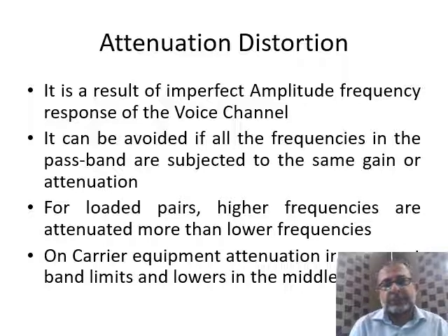Similarly, for loaded pairs, higher frequencies are attenuated more than lower frequencies, and there is a very valid reason for that. In the loaded pairs, we have inductors in our loop, which cause the attenuation of the high frequencies more as compared to the lower frequencies.